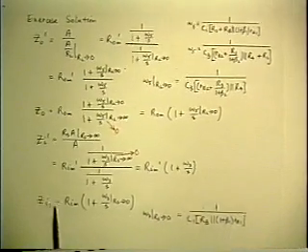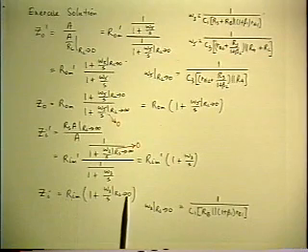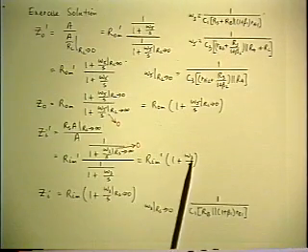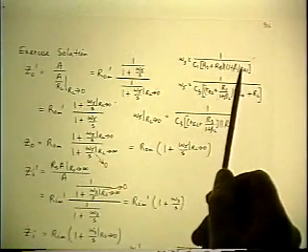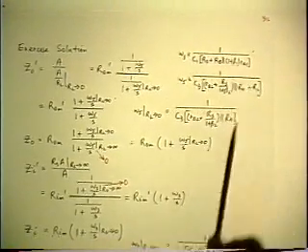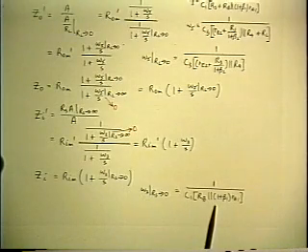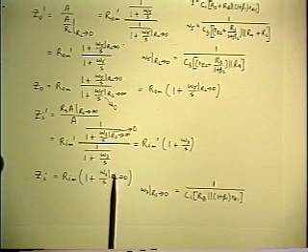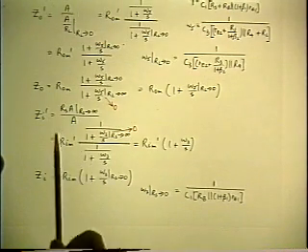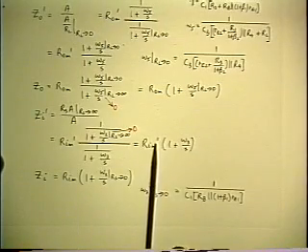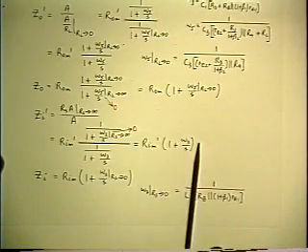And if you want the inside input impedance, you take the other limit in the answer, which converts the mid-band value outside to the mid-band value inside, and you look at the remaining corner frequency, and it still has RS in it. So when you let RS go to 0, you change its value, and you get a new one. So you get a new value of inverted zero. So the conclusion is the inside and outside input impedances both have the mid-band values, which are different, and they both have inverted zeros.